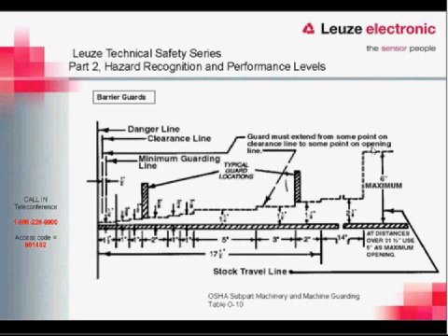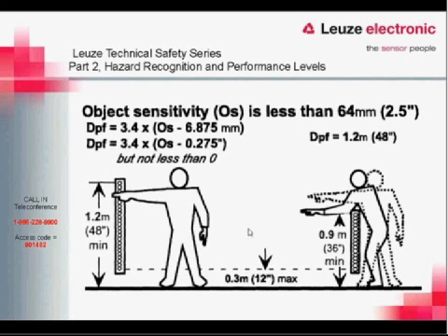So we go to a 6-inch maximum. Anything past the 6-inch maximum automatically goes to a 31.5-inch minimum distance you have to be away. So that's as far as the stick will go to. Usually it only goes to this, the 2 1/8. So if you have one of these sticks, sometimes OSHA will have these with them when they come in and do a check. They'll check to see if they can reach hazards with this stick. If they can hit it with this stick, then you're in trouble. Gotcha.